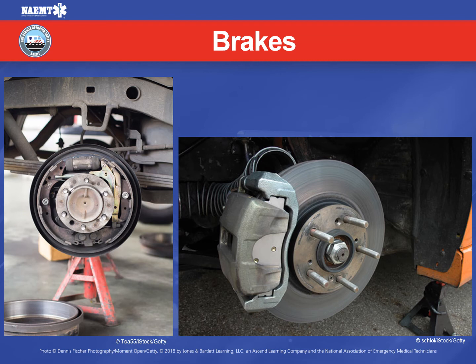Disc brakes are more effective in stopping a vehicle faster because they take shorter brake distances than brake drums. Disc brakes allow for newer technology such as anti-lock brake systems and traction control to be added. Both work off a hydraulic fluid that is forced through the system and squeezes the piston or caliper and causes the brakes to grab the drum or the rotor.